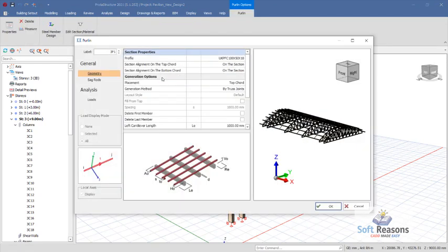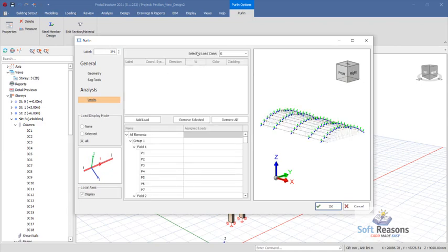select each property. So now come to load provisions. You click on add load. Now you can see we are now having L1 as the load levels. Okay, and then you see we have the selected load cases. We have over here the G load, we have the Q load because we have enabled the loading combination successfully. Okay, assuming we also enable the wind load loading combinations, we could have been seeing WX, which is wind load in the X direction, and WG successfully.